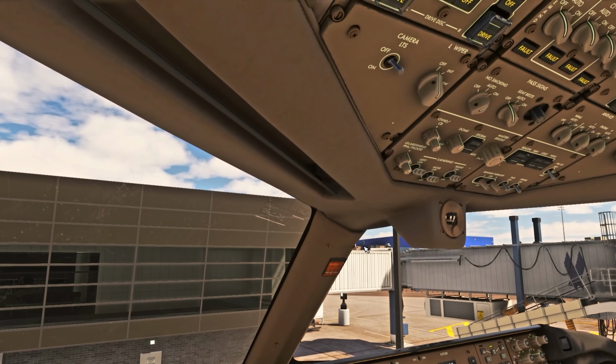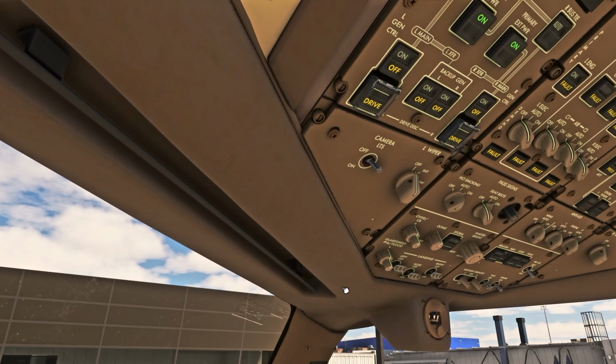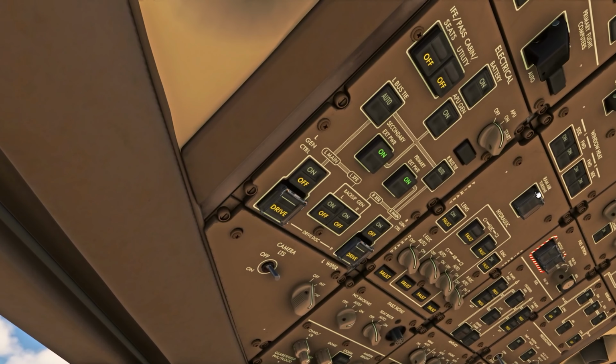So the final step of this, it doesn't have to be done immediately because it burns fuel, is to start up the APU. And that would be our final power up. Generally, I hold off till I'm fueled and a lot of passengers are on board, because if you're sitting there at the gate with the APU running for an hour, you're going to burn a couple hundred pounds of fuel, which can put your calculations off. So I usually hold off with this, but I just want to demonstrate for power up purposes.